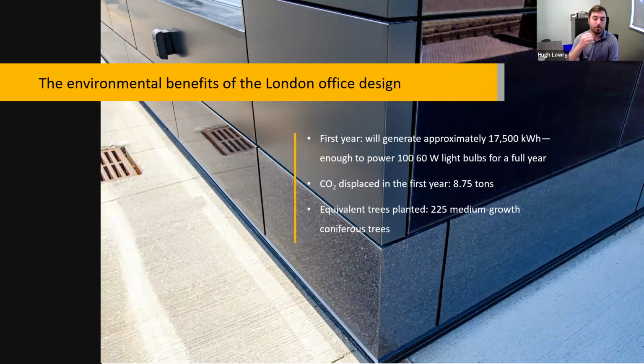What you're seeing in this picture, and what I'm alluding to, is the fact that it'd be really hard to go around the corner with the solar panel alone because you're not able to miter it into a nice, neat corner. What you can see here on the bottom is that Cambrian black granite mitered to a nice, neat corner. Right above that, you can see the ACM that is back routed and bent into place. Both of those materials allow you to finish off that corner very nicely. So they are great filler materials to help accommodate building features that solar panels can't accomplish.